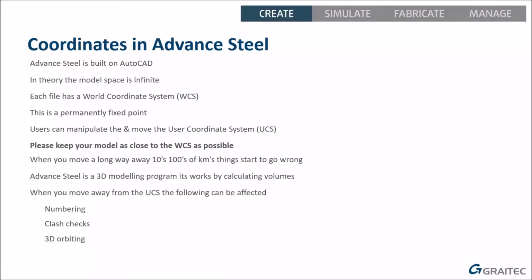We'd done some of the train platform extensions that were happening around some of the bigger stations in London. So we modeled those platform extensions based off a central point in London, and then the stations would be, it wouldn't be 100 kilometers away, but 10 kilometers away, 15 kilometers away. When we went to rotate, the model physically started bouncing around the screen. When we went to number, there were two items in the model that we knew were identical, but the system was giving them different numbers.